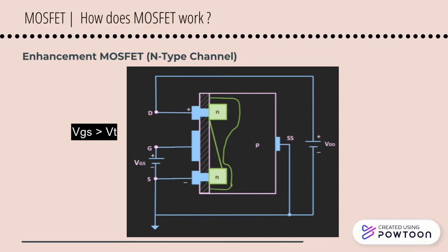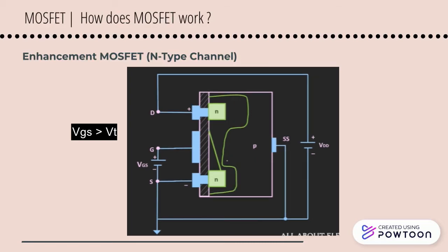The channel is created between the drain and source terminals at the threshold voltage. When we increase VDS and fix VGS, the voltage difference will reduce below the threshold voltage, and the channel pinches off towards the drain terminal. It makes the current through the channel become zero. Current will still flow through this channel and this ID will get saturated because the electrons can still pass through and cross the depletion layer due to the electric force.